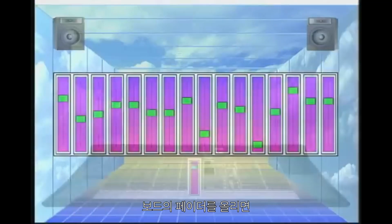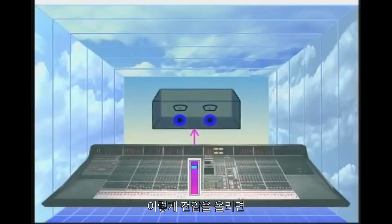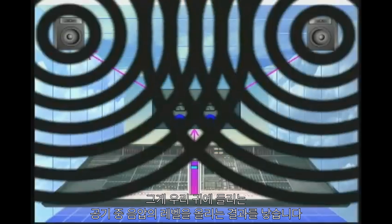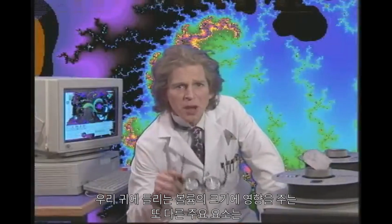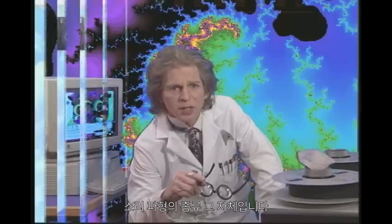When we raise the faders on the board, we are changing the voltage of the signal being sent to the amp, which boosts the wattage, which then sends more power to the speakers, which create more sound pressure level in the air that our ears hear. However, there's more to it than that. The other main thing that affects apparent volume is the waveform of the sound itself.